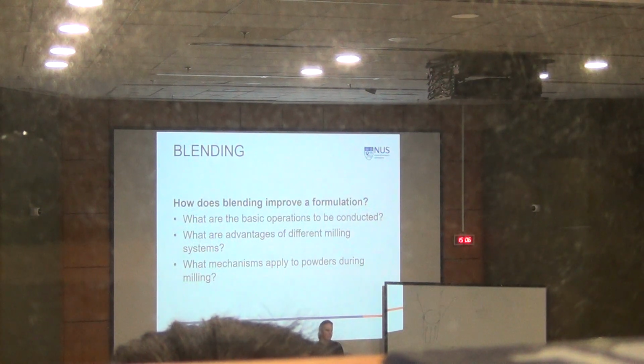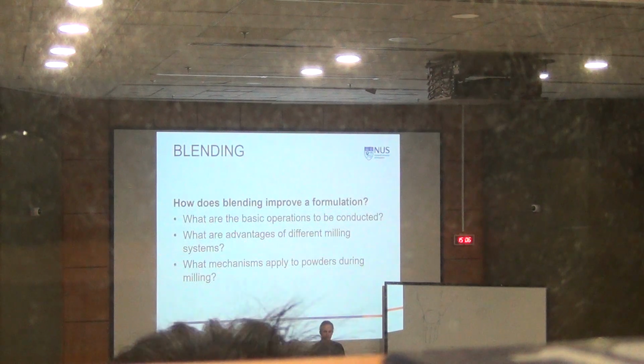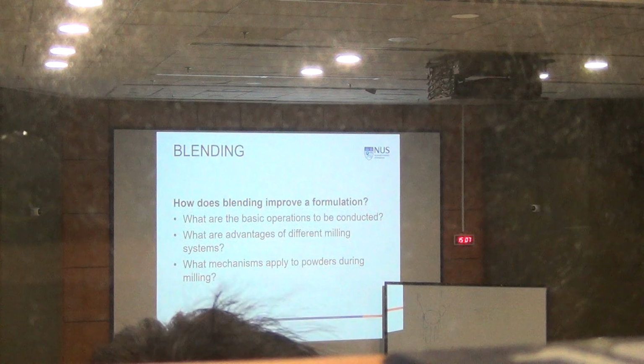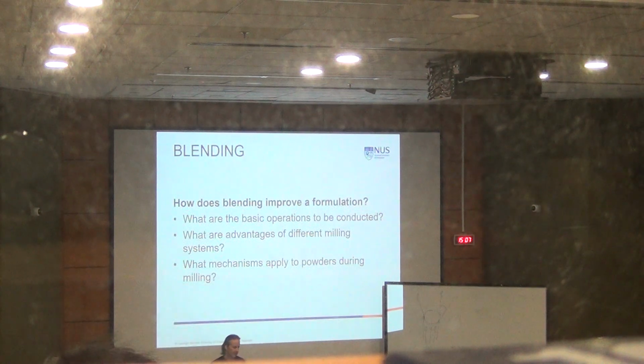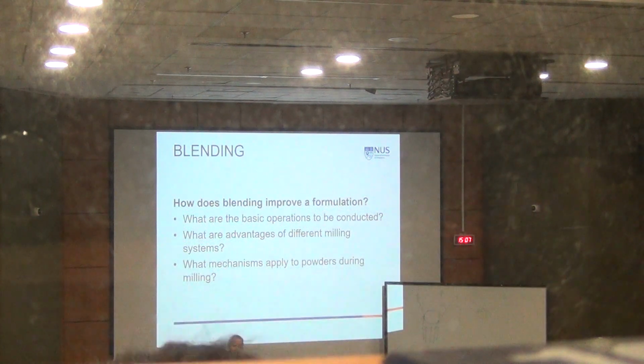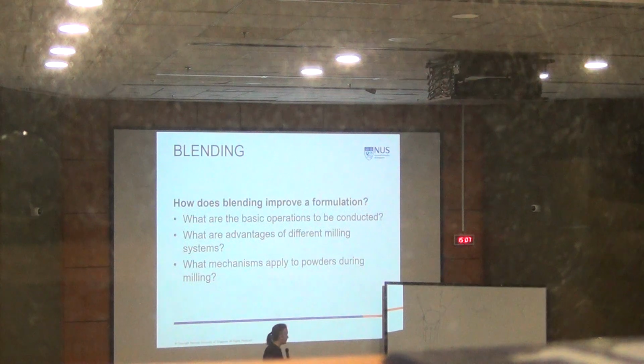We particularly talked also about the effect of overmixing. This is something that is sometimes not really recognized. With common sense, you usually don't expect that longer mixing times can sometimes end up with a worse outcome in terms of the powder homogeneity. So the idea is that sometimes an effect occurs, for example, I think I talked during the lecture about magnesium stearate.